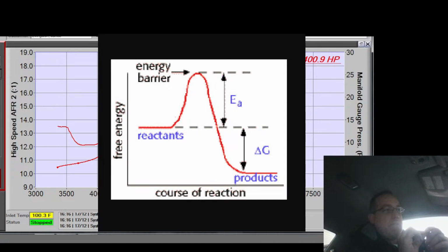And then they have buffers where they blow air. They actually physically have just a big cylinder attached to the lever arm of these contacts. And so when the contacts open up, it compresses the cylinder, and they route that air and they blow it at the contacts, because moving air is harder to ionize than stationary air.